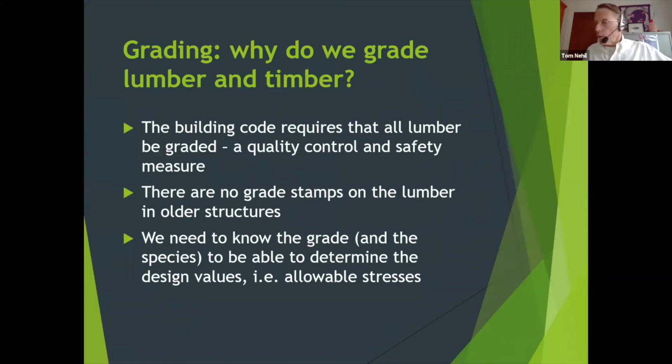All right, well, let's return to grading for a minute. And why do we grade lumber? Why get into all that mess? Well, it's required by code for one thing, and that's a basic safety measure, a quality control measure to make sure that poor quality lumber is not being used where a better stick is required.